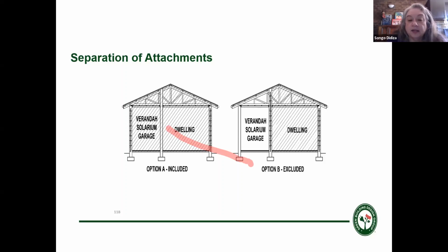It's part of the house. And then your external wall and your windows and all that has to be compliant to 10400XA. If you enclose your veranda, you just put down those blind things or the stuff that stops the wind, because you want to now make your veranda into a place where you can braai, then obviously it doesn't have to be energy efficient because it's not a living area, it's not a living space.